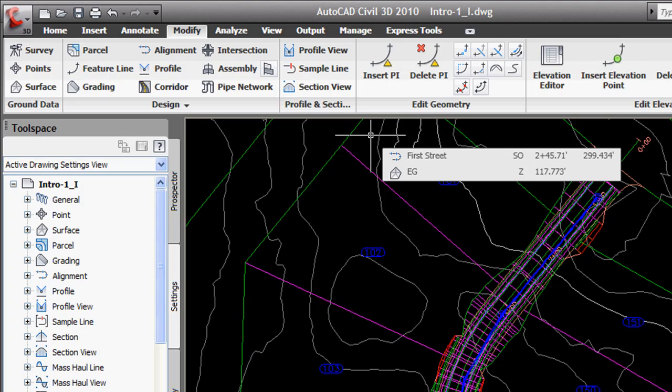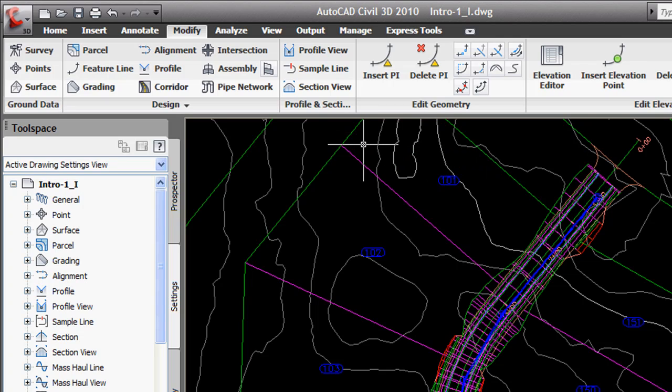So when we're working with items within our drawing, we have 2 options really. I can decide on an action that I want to perform, or a command I want to use, same thing. So I select the command or the action, and then I select the objects I want to perform that command or that action on. That's called verb-noun selection. We select the verb or the action first, and then I perform it on certain objects, which are the nouns. And we can also do the reverse. I can select the object first, and then I can perform edits to the object. So that's noun-verb selection. And depending on which one of those workflows you use, you'll see slightly different options on the ribbon, which are organized quite conveniently for you.